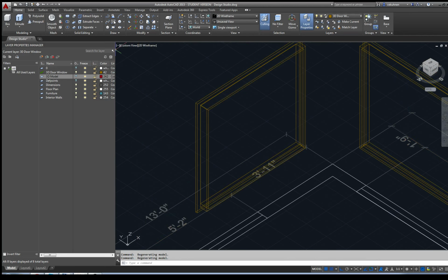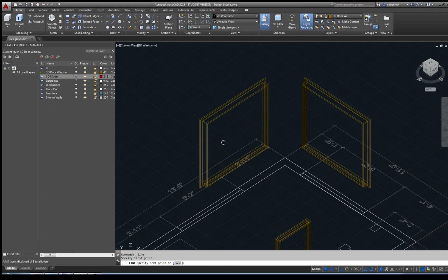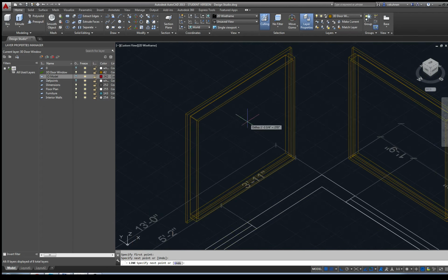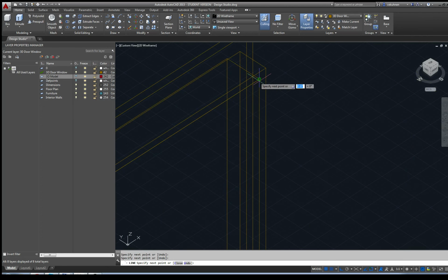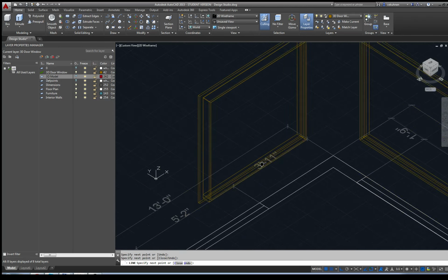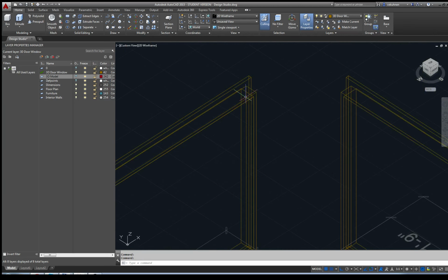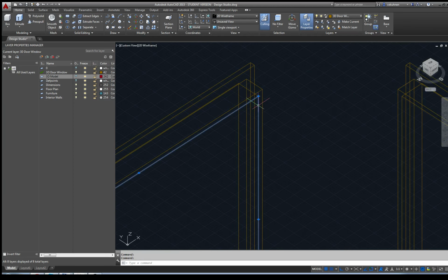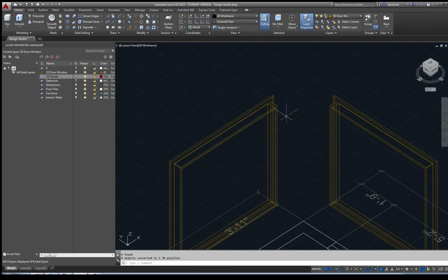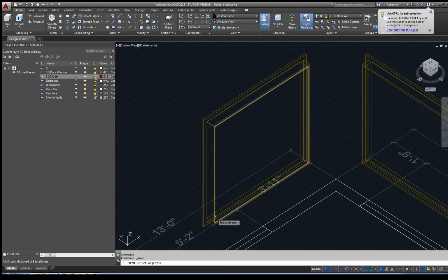And then I go to another drawing and say this point, this point, this point. I think, yeah, this point, back to this point, escape, 1, 2, 3, and 4, join. And to make life easier a little bit, I'm going to select it from there and move it out.